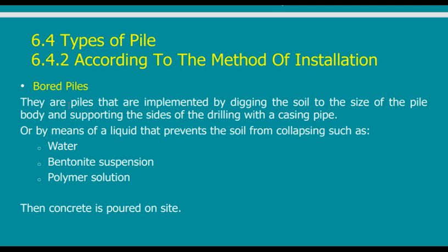They are piles that are implemented by digging in the soil to the size of the pile body and supporting the size of the drill. If I drill a hole and I leave it for 5 minutes, it will close. I will not have the time to drill and then go away, bring my reinforcement, put it, and then bring my concrete and put it. I don't have the time.